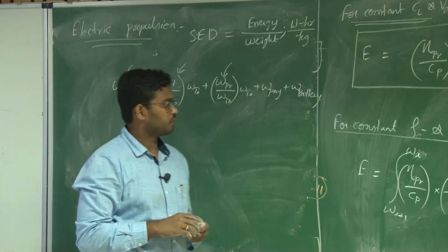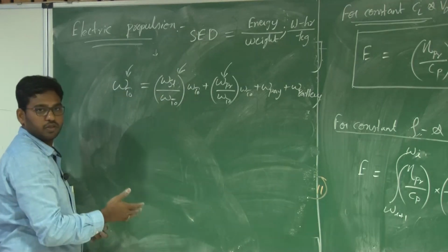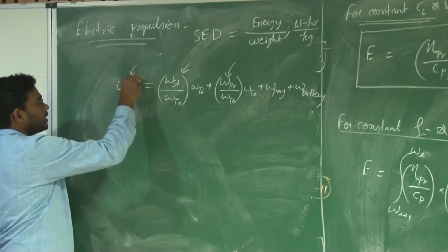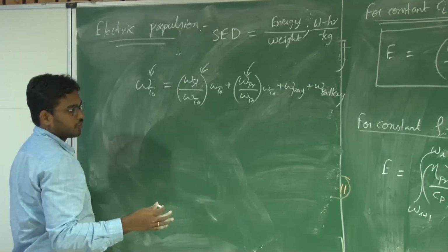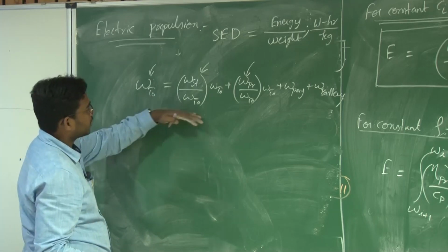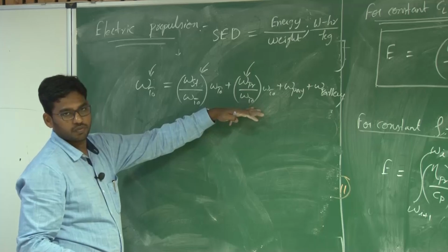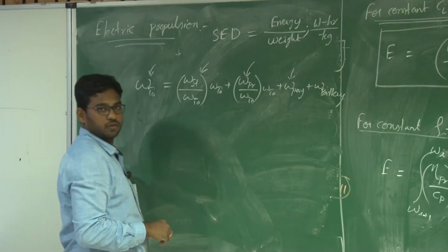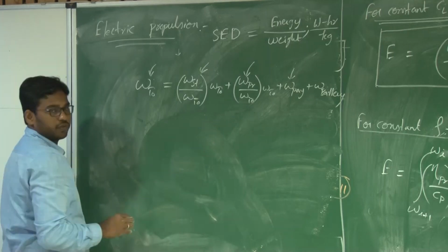How? We take the nearby flight vehicle which is performing a similar mission, right? So we will take the weight initially from the historical database, even the overall takeoff weight. At the same time, we will take the structural weight and the propulsion weight, right? And the payload is given for you, right? So let us say these things are known for the time being.